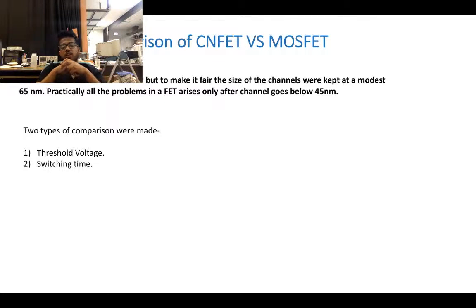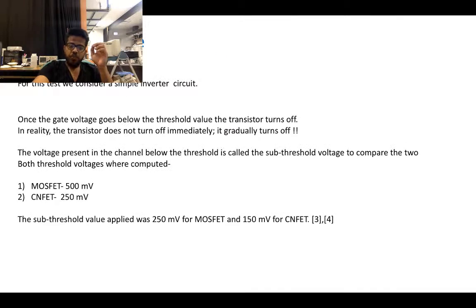So two parameters were taken into consideration. One is the threshold voltage, the voltage at which the transistor turns off and on, and one is the speed at which it does. For the threshold voltage, they considered a simple inverter circuit to see how fast it inverts from 1 to 0, or how long it takes, or what amount of voltage it takes to convert from 1 to 0. Now, as I mentioned earlier in my presentation, there's something called a sub-threshold voltage. What actually happens is when you turn off a transistor, it does not really go back to zero at once. It gradually turns off.